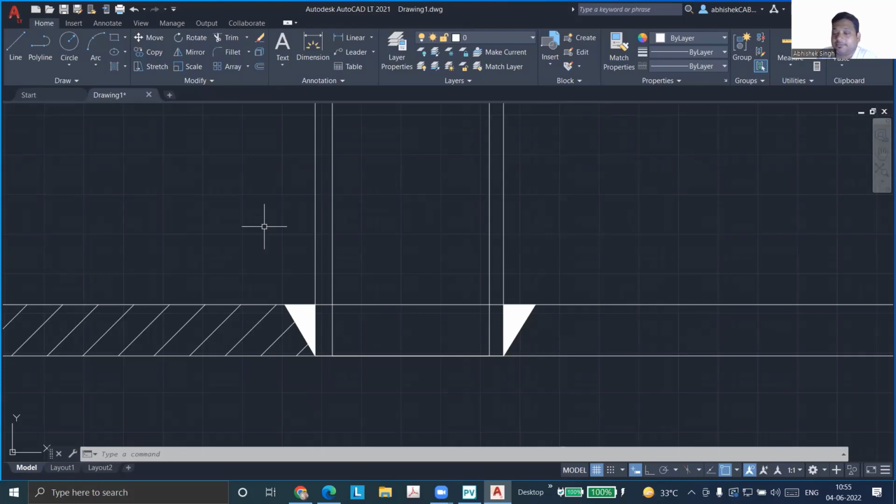It will give me a film. But to interpret the film, to see whether cracks are there or not, that is also a study, right? The radiography people are qualified based on whether they can interpret the film, isn't it? So their qualification is based on that. So it's not red and white.